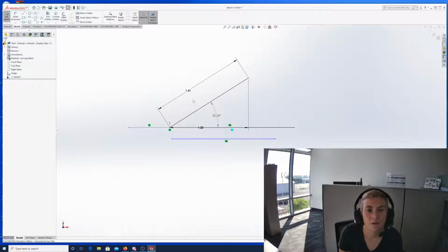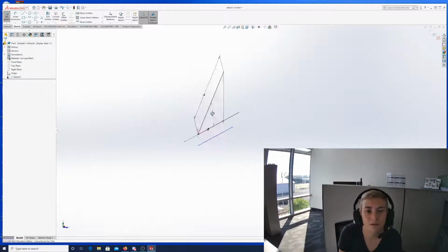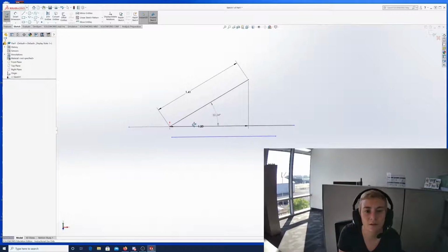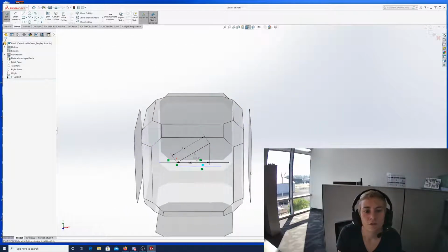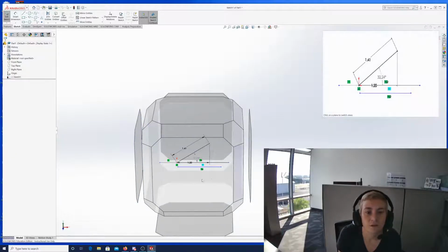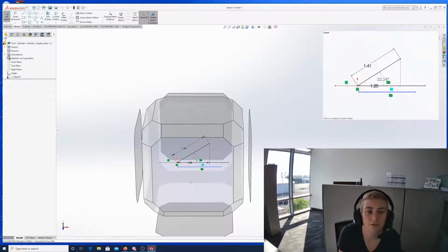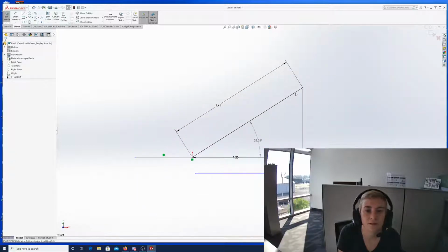And then if you click the scroll bar, you can drag your picture around. So I'm holding down my scroll bar and you can drag it so you can see it from different angles. And then if you want to get back to the front of your drawing, the plane that you were in, you can go to this cube up here. View orientation is what it's called. Hit the little down arrow and it's going to show you each side of basically a cube that your drawing is in the middle of. So click the front face of that and it'll bring you right back to the front.